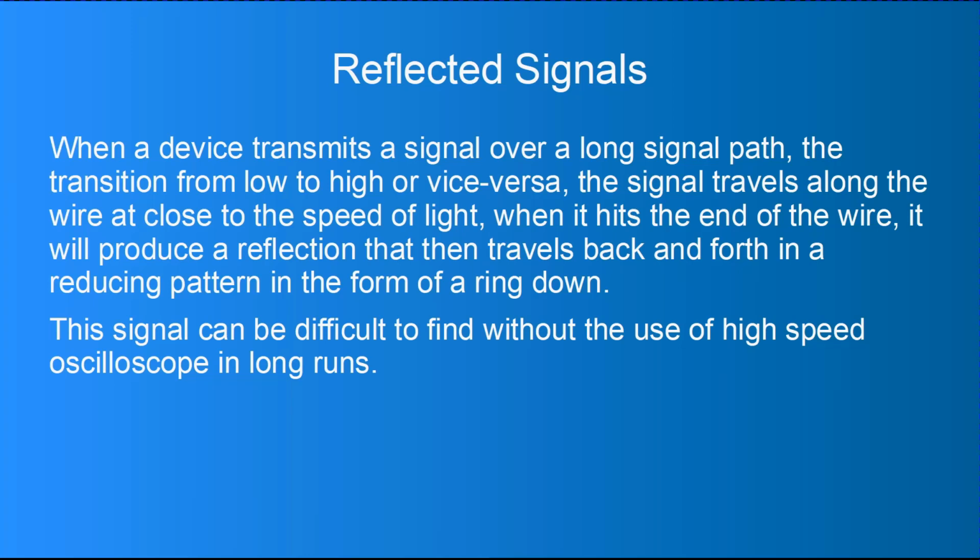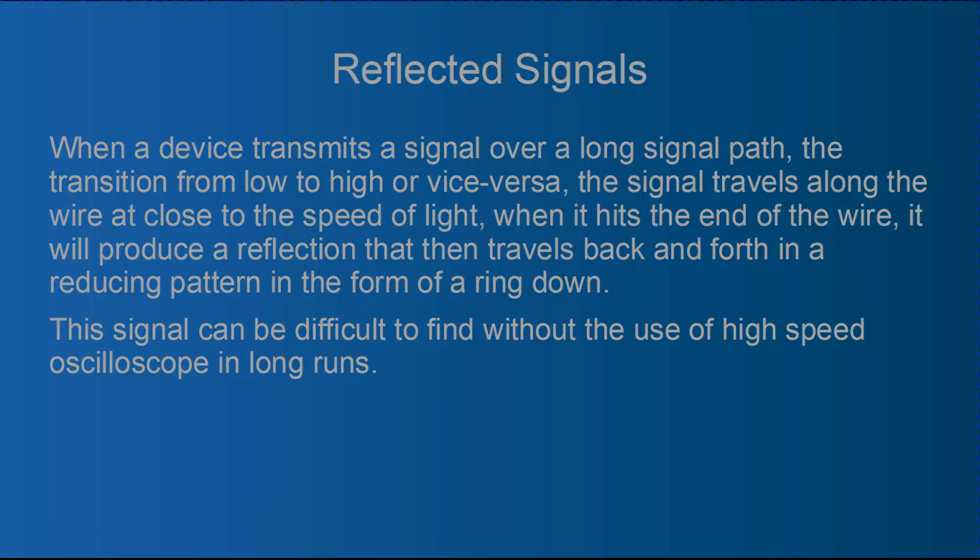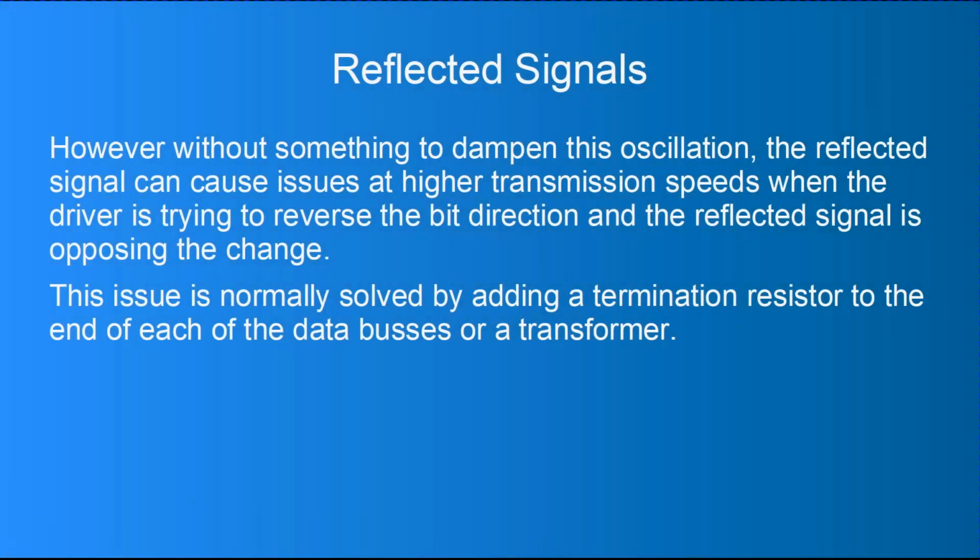Now there's a couple of ways we can try and mitigate this problem, and the most common one is to add resistors at the ends to bleed that voltage down to ground. The other method is to use transformers at the ends and look at current flowing. You don't need much current with a transformer. You just need some, like if you use a larger turn ratio transformer. And the RS485 standard says to use 120 ohm resistors at each end to help reduce that.